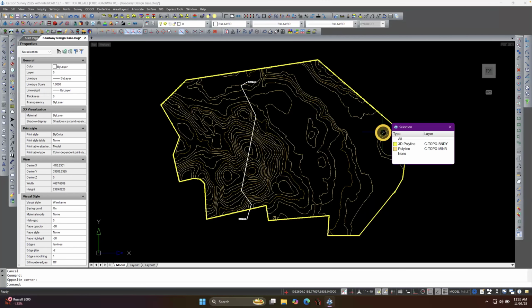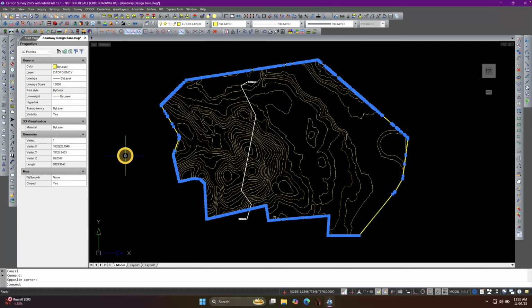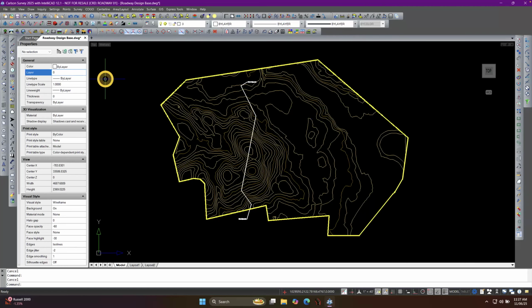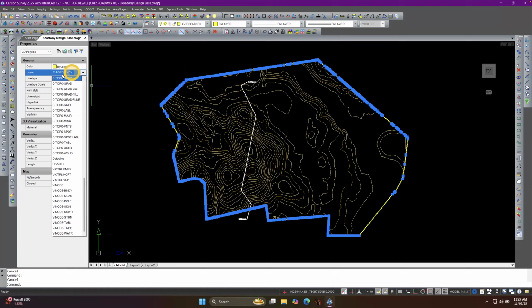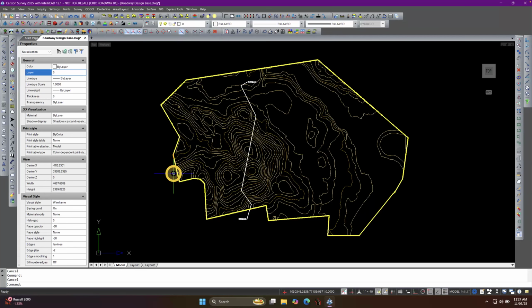We have this polyline. If I look at that polyline, I've got this 3D polyline. It's on a layer called C-topo-BNDY. So my C, which stands for civil, and they usually might propose types of layers, but C boundary. So it's my civil topo boundary. So you see all these layers that are pre-built. And that can either be part of your drawing template, or in this case, it was part of our drawing that we got from somebody else.